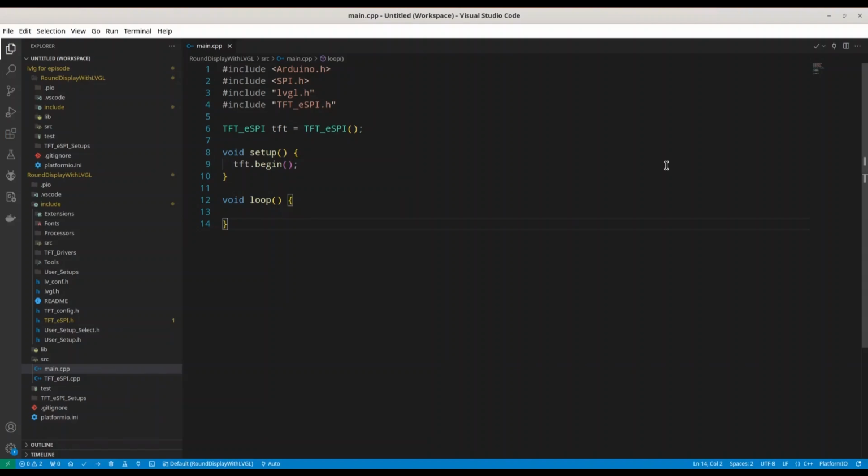And you could get some really nice and good looking images. But those images cannot be processed in raw form. We have to provide images in something that is called C array. And in this episode I'm going to do exactly that. I'm going to show you how to properly format images for your TFT and how to draw them. Basically, we have only two interesting functions.